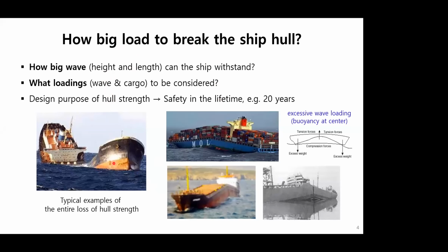In other words, what type of wave and cargo loadings should be considered for the hull structure to be strong enough and guarantee safety. Design purpose of hull strength is to ensure safety in the ship's lifetime, 20 years.